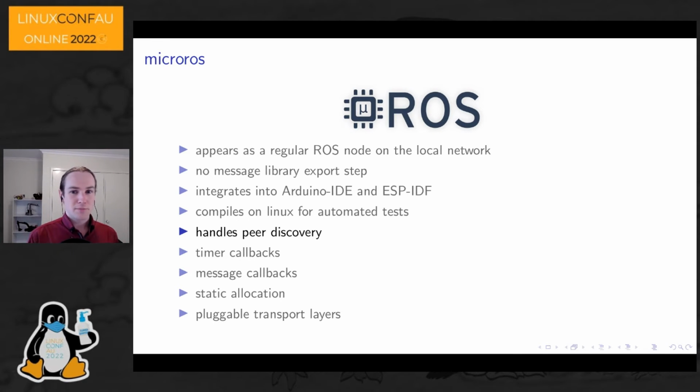Peer discovery is important for flexibility. By forcing a decade's worth of robot developers into a strict and modular design pattern, any host-side nodes ever written can talk to any microcontroller on the network without modification. micro-ROS integrates with FreeRTOS, so you can have fancy threading stuff, or you can just write event handlers.